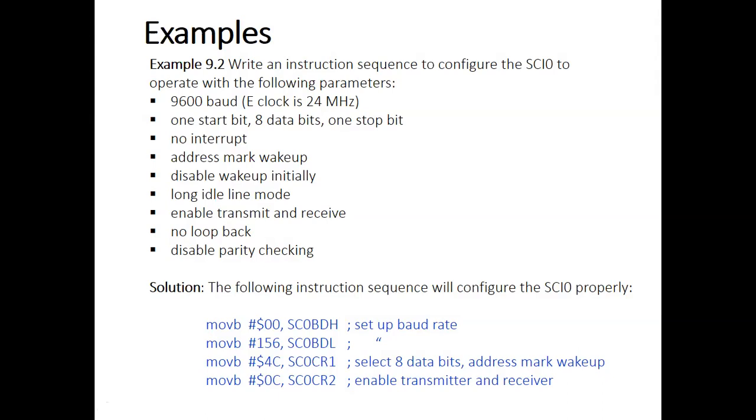The data format is one start bit, 8 bits for data, and one stop bit. So basically the data is in 8-bit format, not 9-bit. No interrupts, and address mark wake up.